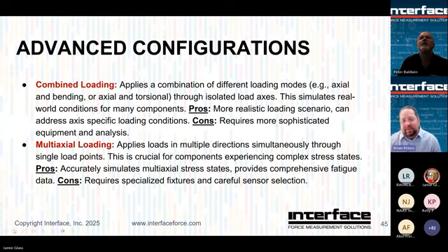So that kind of leads to the next test setup here, which is multi-axial loading. So maybe you have a single boundary condition where you're anchoring the test article, but you're actually imparting multiple forces through it, and now your reactive or anchor force is seeing multiple axis loading at the same time. So we do offer a wide range of multi-axis sensors, so we certainly can do it. Just have to pay attention to a couple things there.